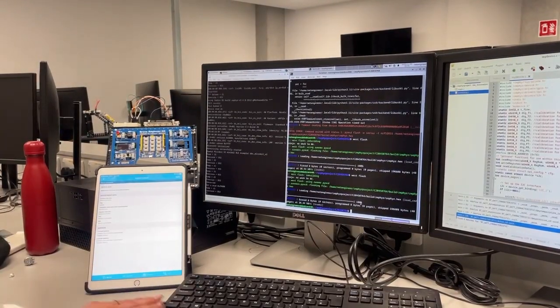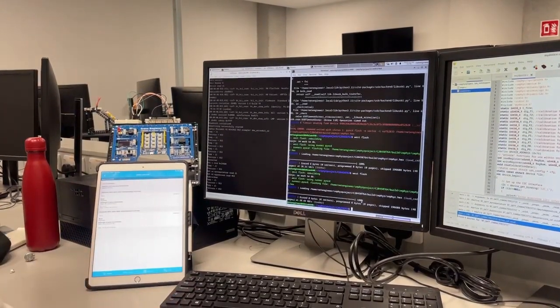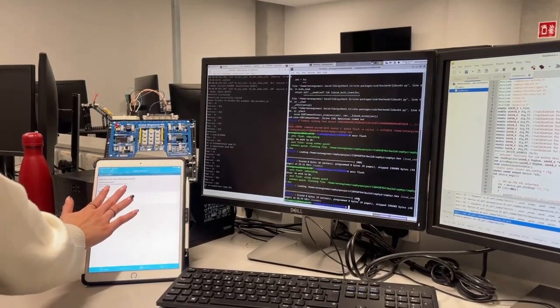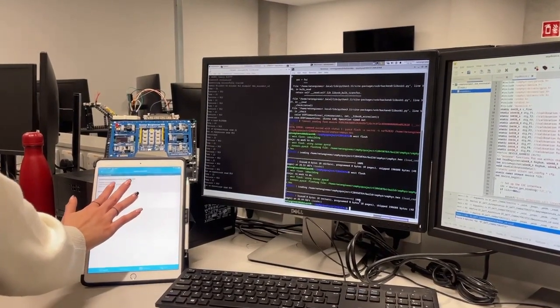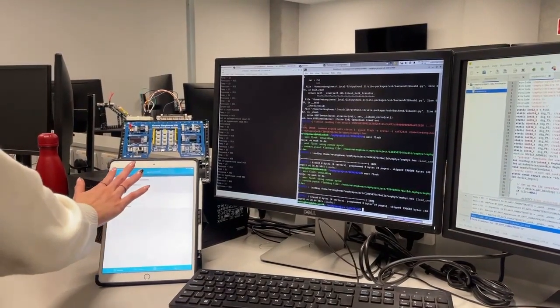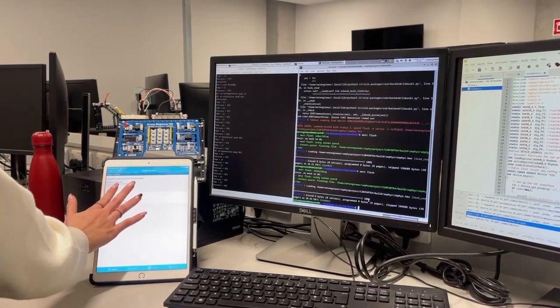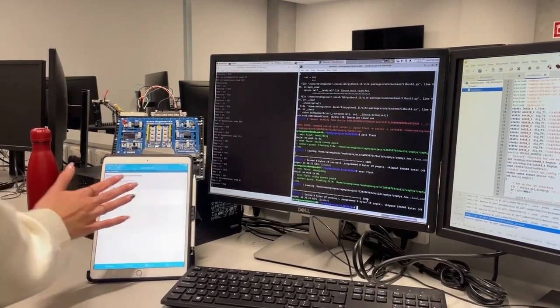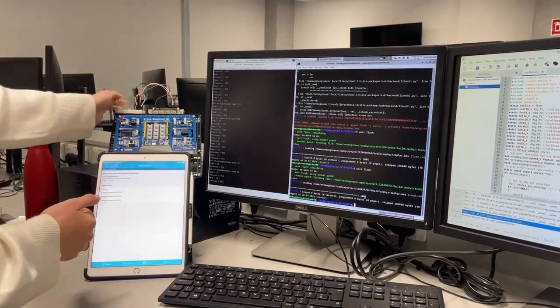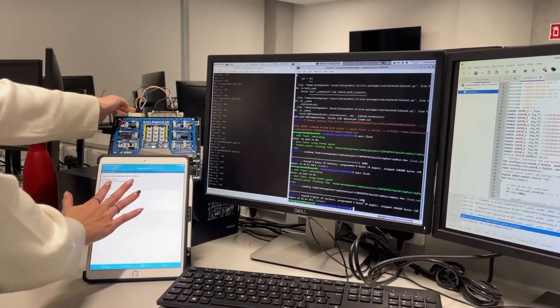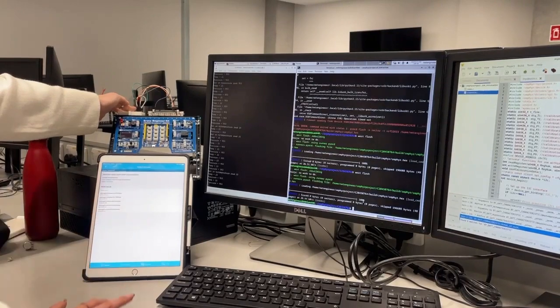On my iPad on BLE Scanner, I find Sandra's microbit and click into it. There I find the service number 9000. When I click within it, I find 9001 and 9002 as I defined in my code. As I press into each characteristic, an output appears on my port registering that an output has been made, and it also appears on my iPad in hexadecimal format.